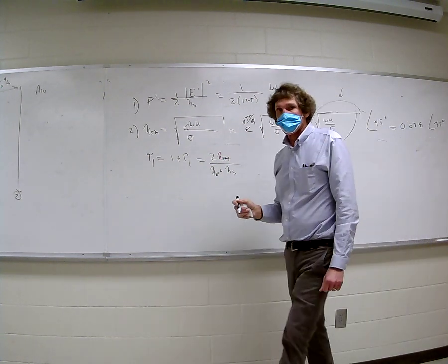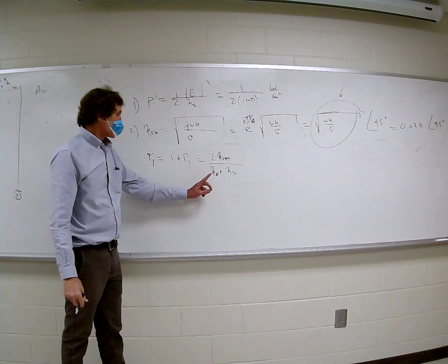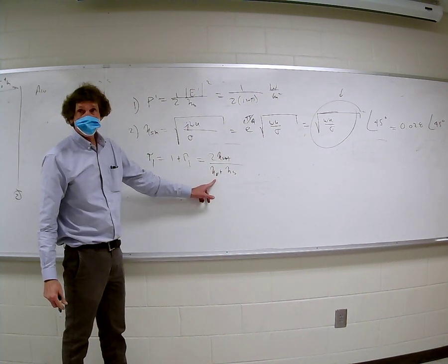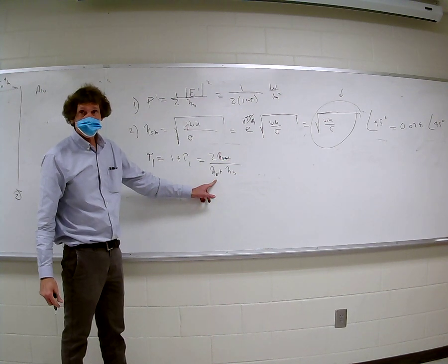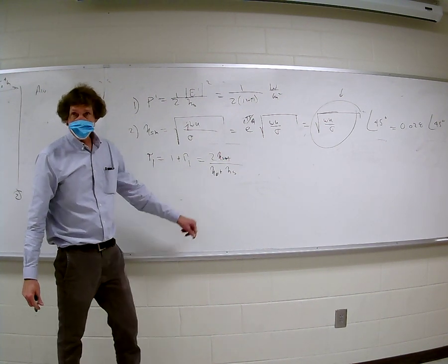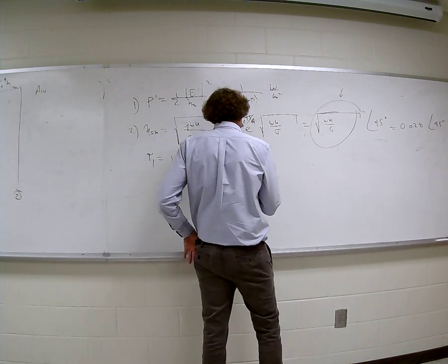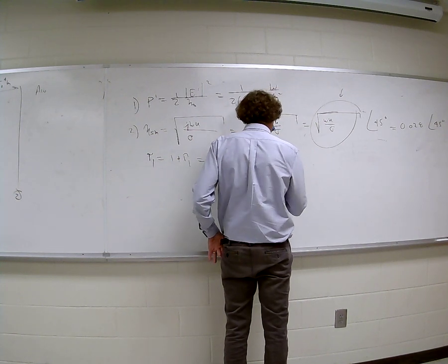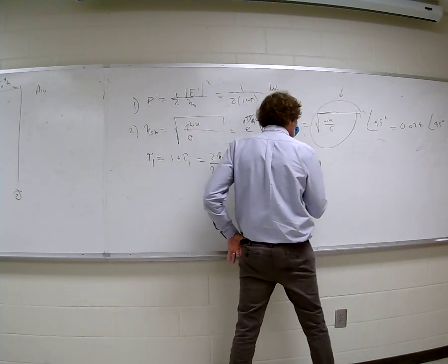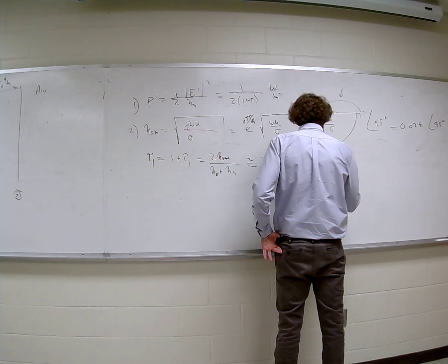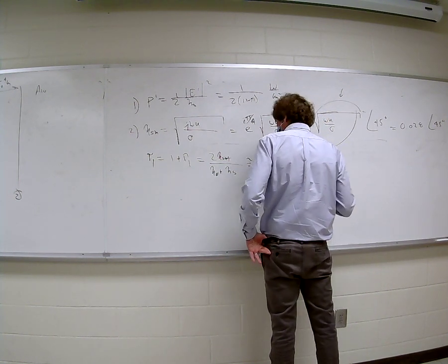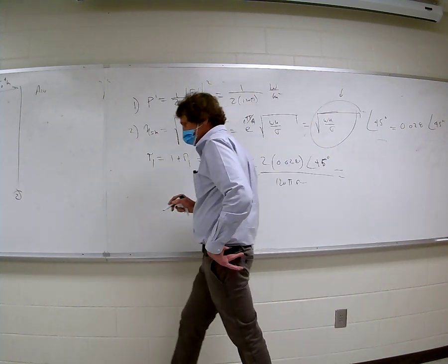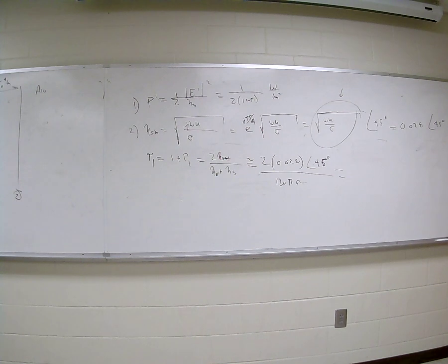Now, we're rational beings. If you look at this, 0.028 plus eta naught, 120 pi, about 377, is about eta naught. Do you agree, class? So no matter what approximation you make, you get the right answer. So this is really about 2 times eta shield. So it's 2 times 0.028 at an angle of 45 degrees. Remember, this is complex. Over eta naught, or 120 pi. That's about what it is, and it's going to be almost exactly that for this problem.